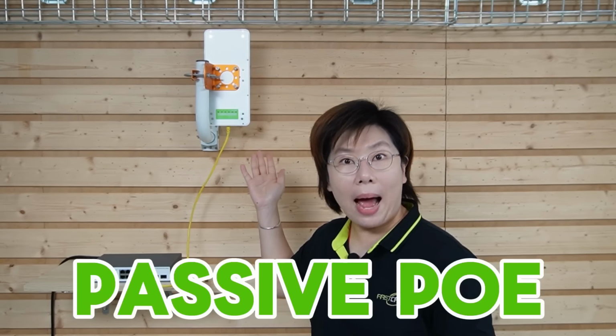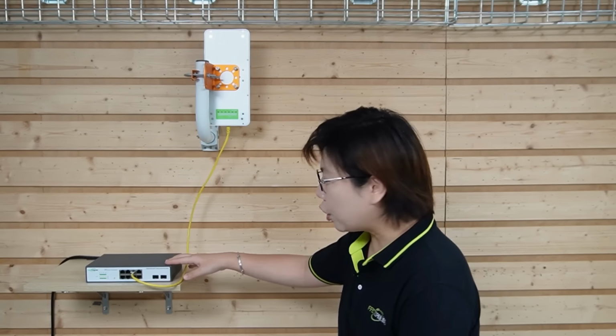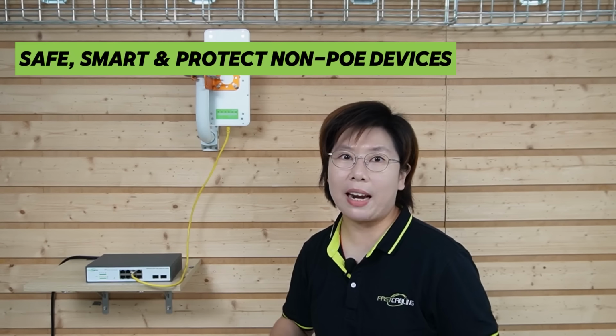The twist is that this bridge uses something called passive PoE. To understand why it failed, we have to look at how these two technologies talk to each other. On the switch, we have the active PoE. This is the smart handshaking type. When you plug in a device, the switch sends out a small voltage, checks for a specific response like a digital handshake, and only then does it send the full 48 volts. It's safe, it's smart, and it protects non-PoE devices from getting fried.